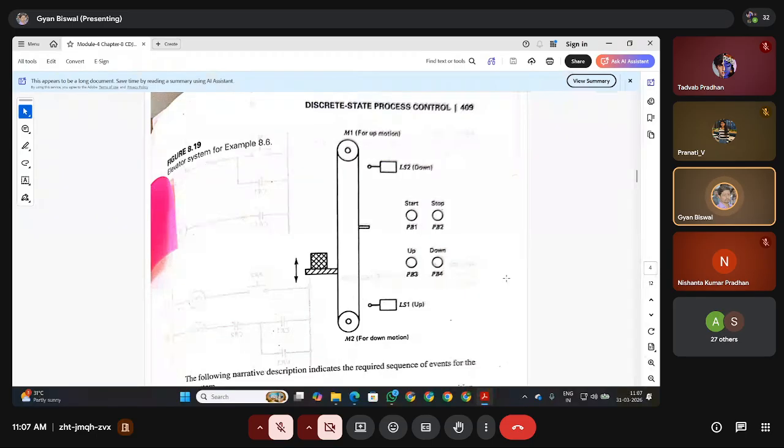It should reach the safer point and then the door should open so that the passengers can come out from here. Then either it can be closed or, on the safer side, because it is a power failure, it should remain open, right? If it is happening on the top floor, then in that case the elevator should automatically reach the ground floor, because that is the safest condition, and it should remain there.